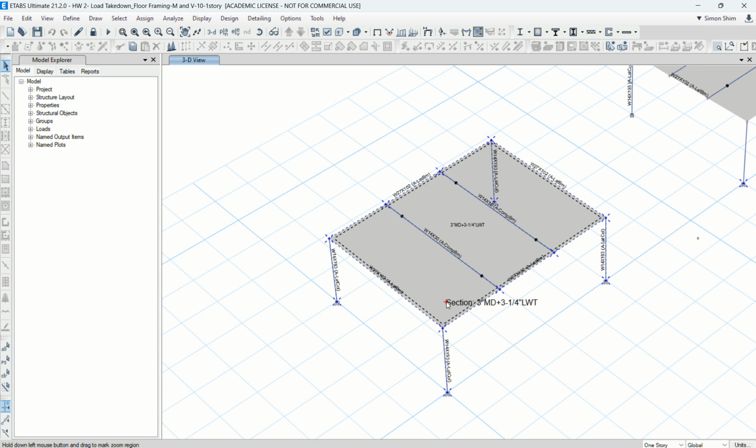But typically, for beam framing, I want you to at least understand clearly today, because you've practiced this a lot. Basically, 99% is something like this, right? If you're living in a dormitory or house, your beam, wood joist, is a simply supported beam. They don't have rotational resistance. It's a simple beam. Then you use wL squared over 8 for your beam moment calculation.